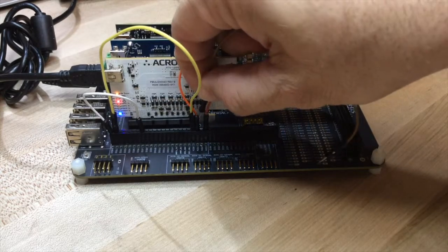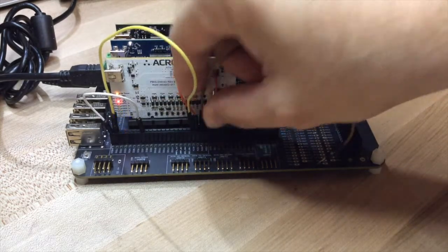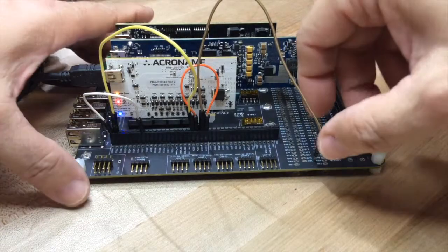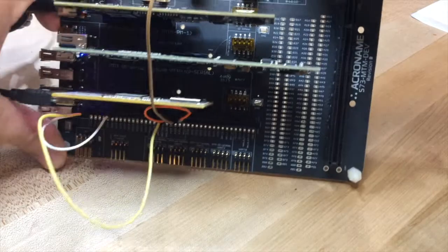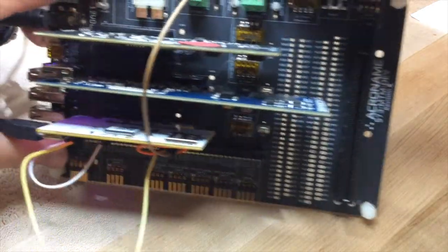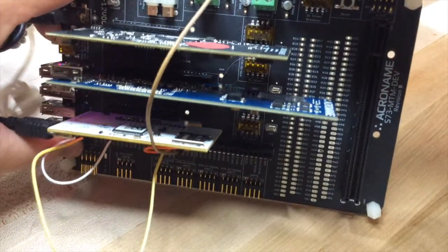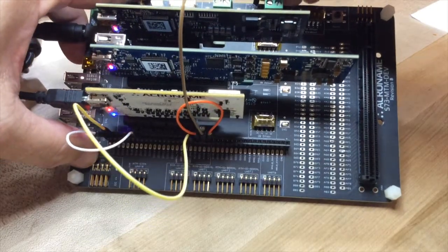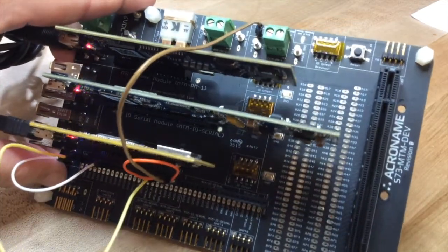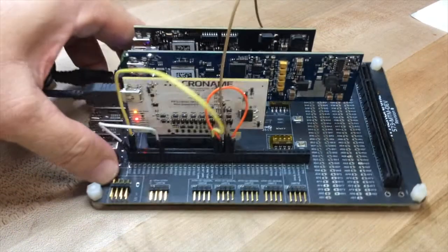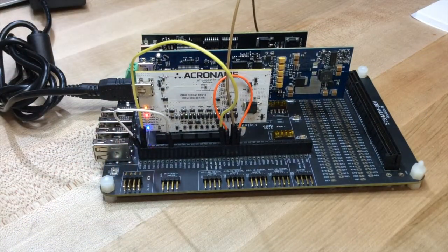For our next exercise, we're going to jump across from analog input 2 over to the back side of the power module, and we're going to read rail 0's power output. You can see where we're tagging down on the MTM development board. We're actually connected to the Kelvin sense output for rail 0.